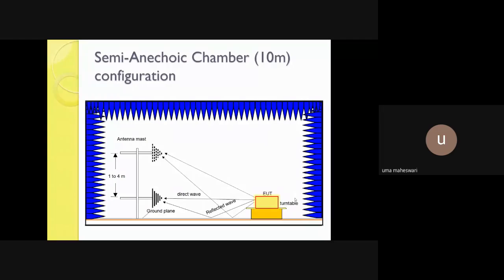For measuring the test results, various equipment are available: EMI receivers, some transducers, PDN, and others for testing the instruments. It can be manipulated with the help of software or correlated testing, and can be taken as a report, which has to be given to the EMC EMI regulations. Regulations means, for example, BS, BIS, FCC, CE, for the certification process.